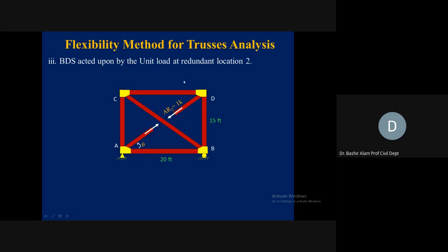If it is leftward directed, here it will be rightward directed, towards the joint, and towards the joint means member CD is coming under compression. Its vertical component was downward, so at D, the member BD force will be towards the up direction, to balance this downward. So it is towards the joint, and towards the joint means FBD is in compression.